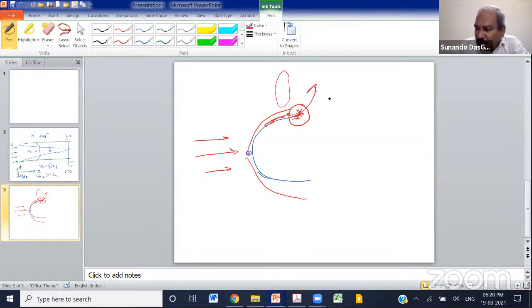Now, whenever this boundary layer separation takes place, there's going to be the formation of wakes, and the formation of wakes are essentially low pressure regions where the fluid particle, due to the presence of the adverse pressure gradient, cannot move forward, and therefore it has to leave the surface in order to satisfy the equation of continuity, because it will be dislodged by fluid particles which are approaching with a certain velocity.